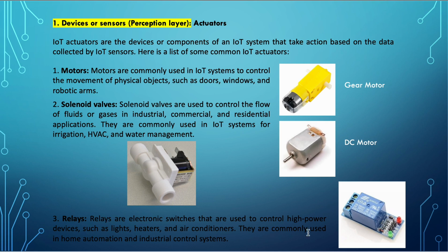So similarly, when selecting relays, we should know the parameters, how much electricity it can handle, and so on. We have to check how much electricity we are going to handle, especially if you are taking heaters and air conditioning units. A relay that is handling heating and air conditioning units in a home will not be able to handle heating and air conditioning in an entire building.